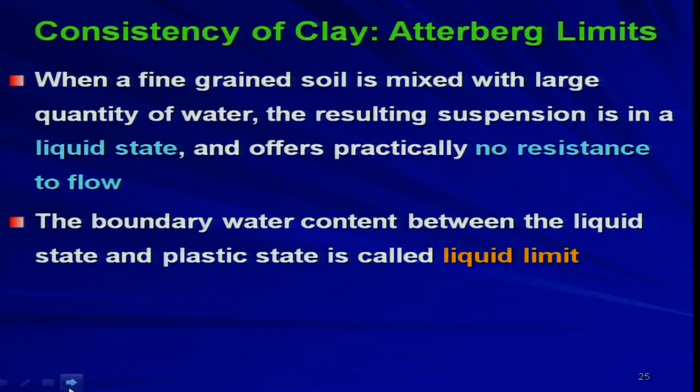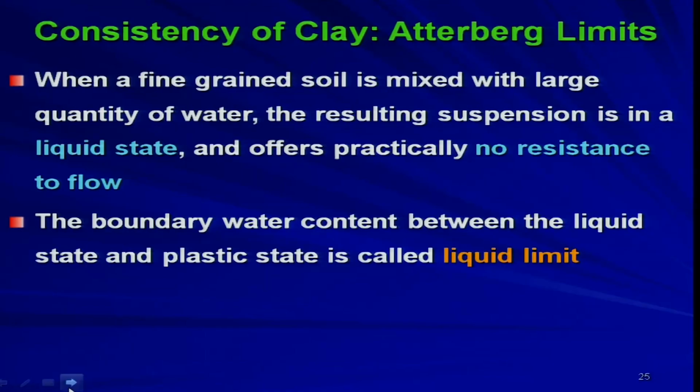Now, when a fine grained soil is mixed with a large quantity of water, the resulting suspension is in a liquid state, as I have just told, and offers practically no resistance to flow. So, in the liquid state the soil will not offer any resistance to flow. You will not get any kind of strength, it is a kind of soil water slurry. So, in the liquid state it will not give you any strength.